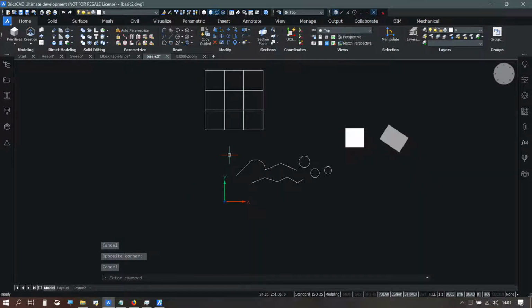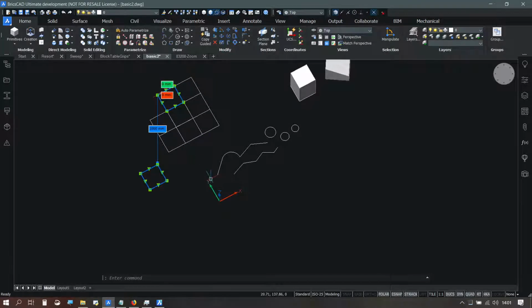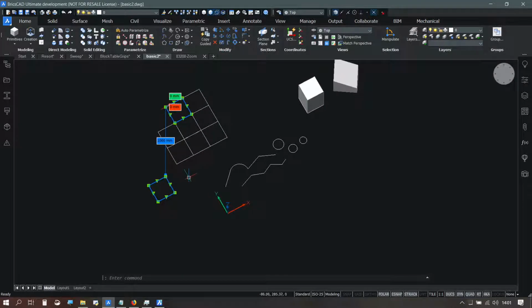But it's not only helpful for horizontal distances like here. If I select two of these rectangles, it says, okay, 0 millimeters. That's as I expect. If I select these two, it says, oh, 0.5 Z difference. If I select these two, 1000 difference in Z direction. So if I rotate, this is typically what goes unnoticed in plans, but what you can get an early warning for with nearest distance. For that alone, it's already worth its money.